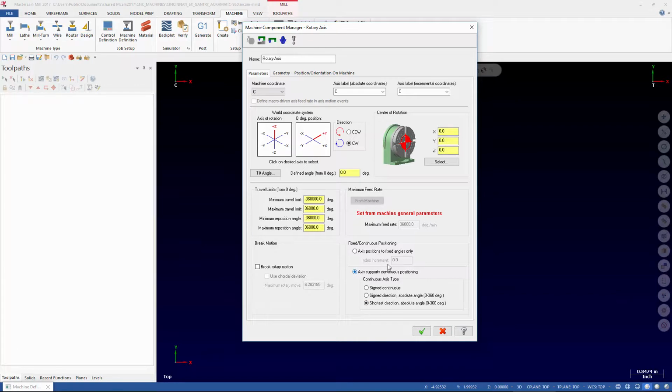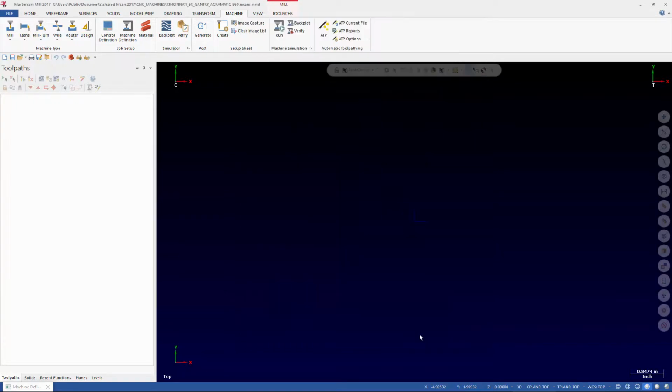Now, what I'm telling you is not true for a 4-axis machine. For a 4-axis machine and a 4-axis generic post from Mastercam or MP Master, data is read for the rotary axis from the machine definition. But it is not for the X-style 5-axis generic post. Okay, so that's an important thing to know. Same with the travel limits. Ignore it. Here I've got it set to Z, got it set to Y, whatever. That's the C.